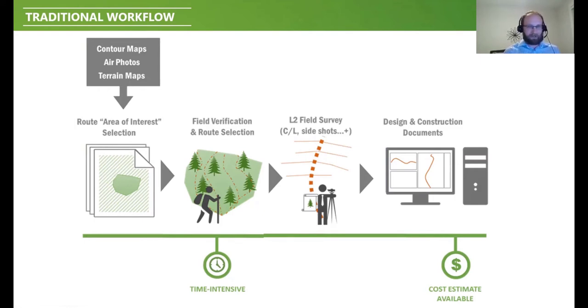ribbon that in. Once you get it ribboned in, you usually do your level 2 field survey, so your road traverse. Old school way being compass, clino, and the tight chain. If you're still doing a hand traverse and you're kind of on the cutting edge of things, maybe you're using a GPS and a laser instead of a tight chain.